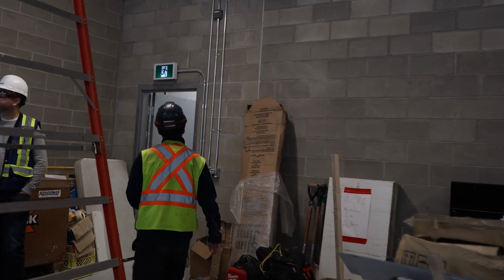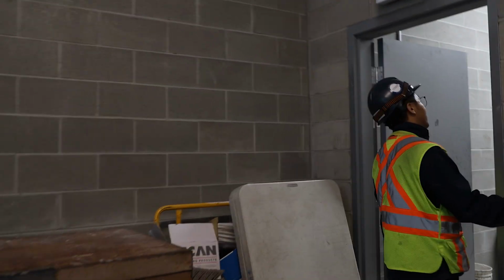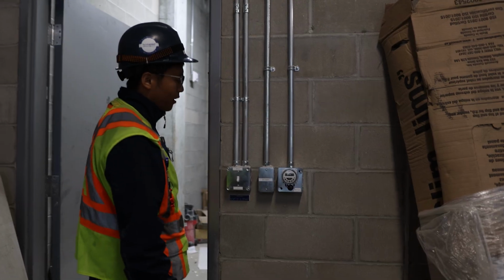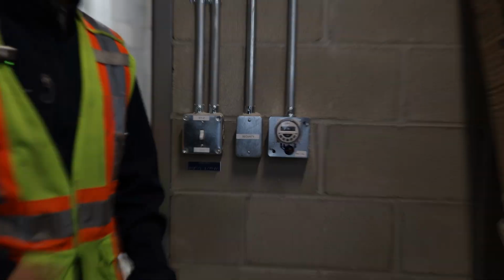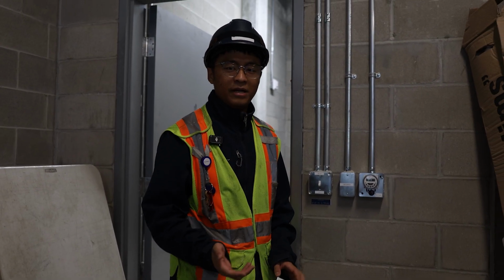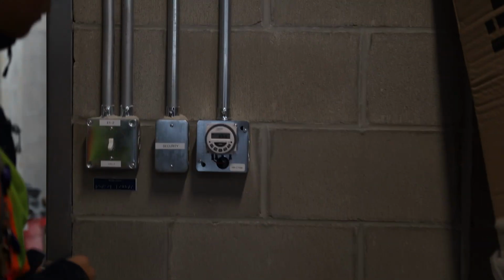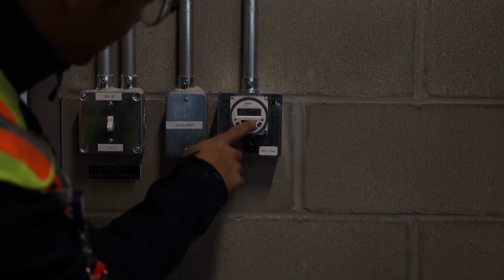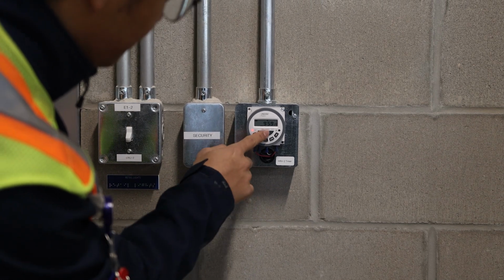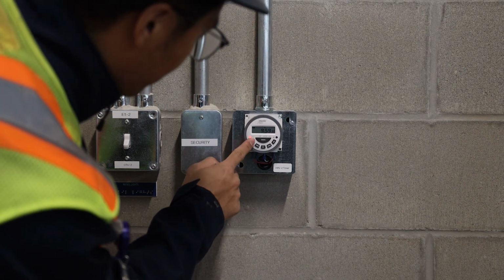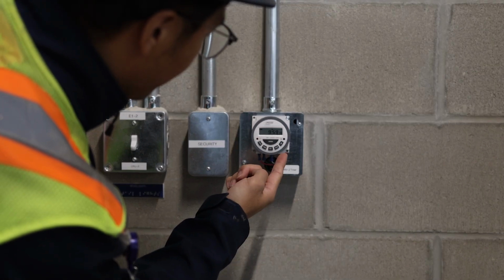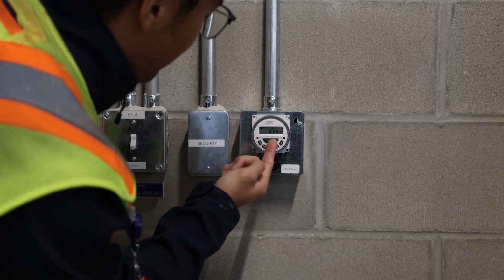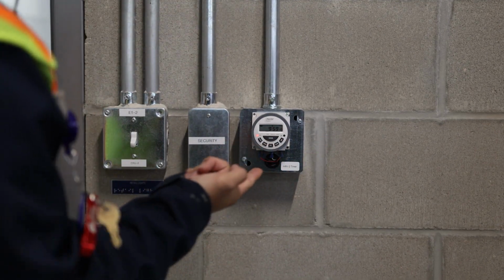If you come closer, this is HRV2, the timer for the HRV2. The HRV2 is also a standalone unit. It's not monitored by the BMS. If you remove the cover, it tells you the time. You can manually turn this on by pressing the manual button, and you can also set the clock. So let me do this. If I manually turn on the